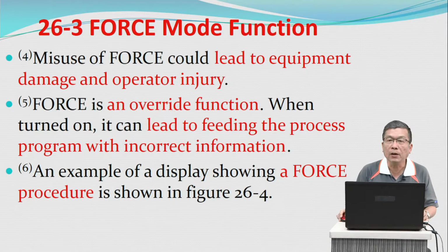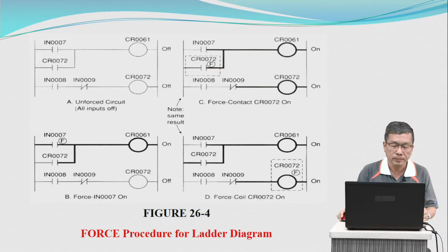Force is an override function. When turned on, it can lead to feeding the process program with incorrect information. An example of a display showing a force procedure is shown in Figure 26.4. This shows the force procedure for a ladder diagram.